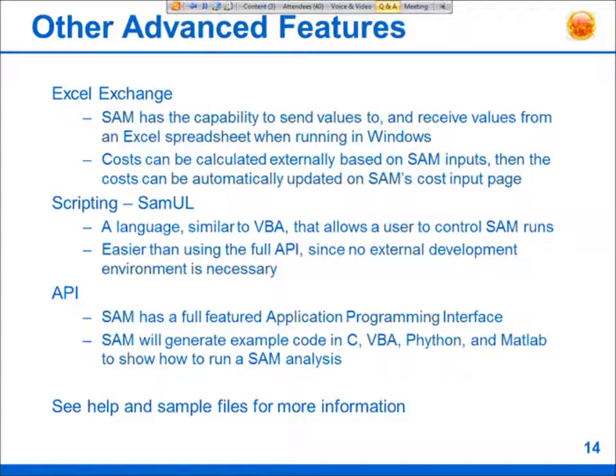There are other advanced features. Excel Exchange allows you to calculate the value of input variables in SAM using an Excel spreadsheet. SAM has a built-in scripting language that's analogous to VBA in Excel. So you can write your own little program within SAM to control the value of inputs, to manipulate or control simulations, and also to extract results and export them to text files.